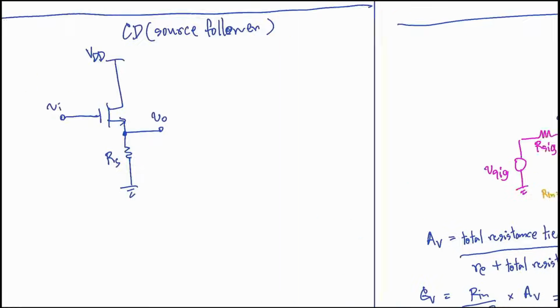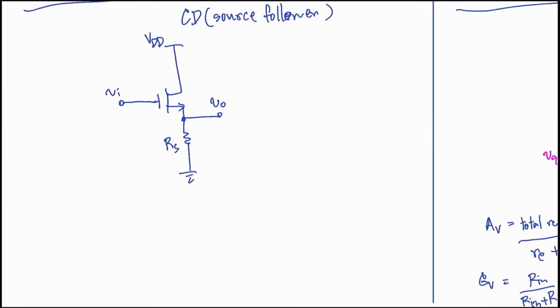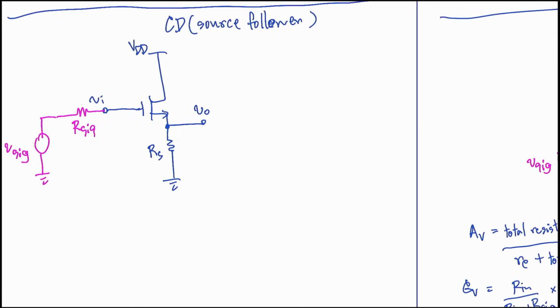Signal voltage, we use pink, right? So let's take a closer look at this specific circuit configuration. First, consider the R input. It is effectively infinity, right? To be more precise, the R input at the gate pin is considered to be infinite, because in this ideal scenario, there is absolutely no current flowing into that terminal.